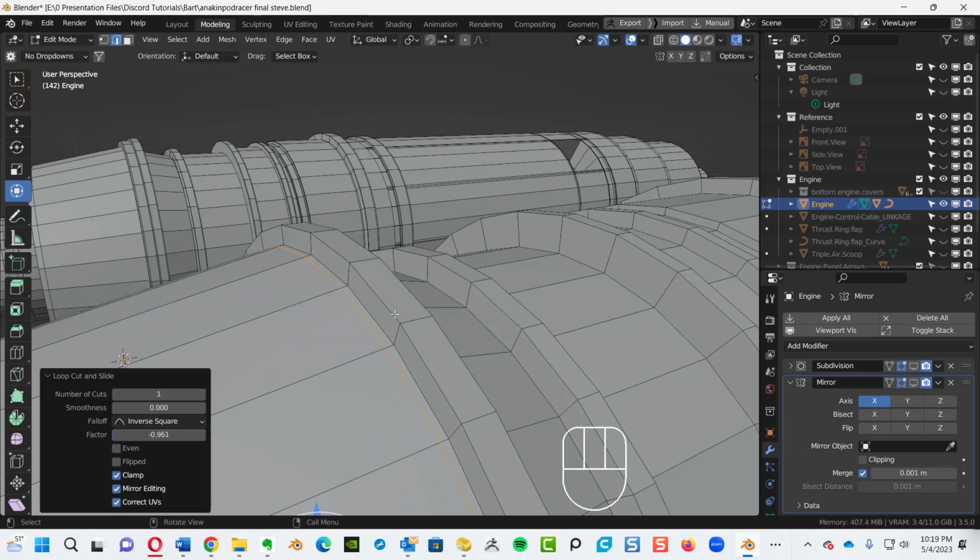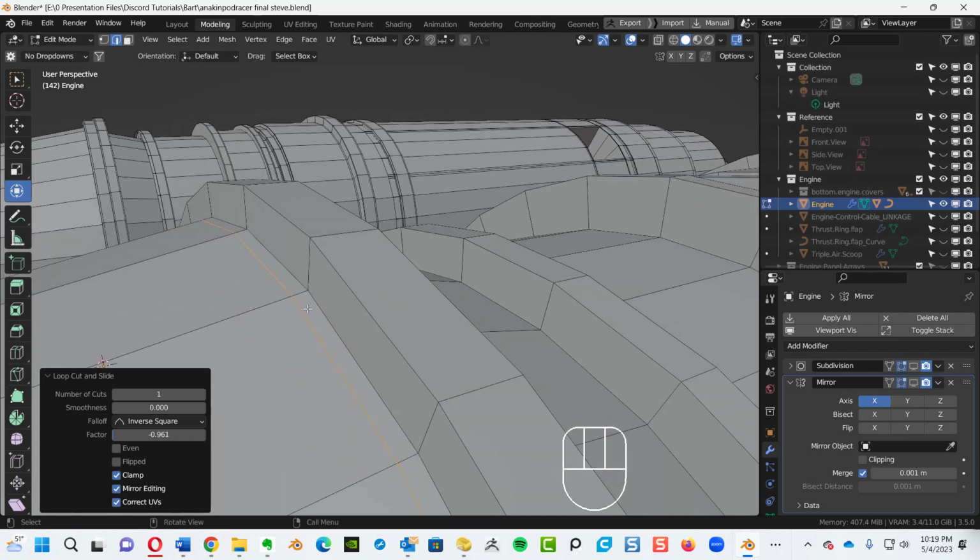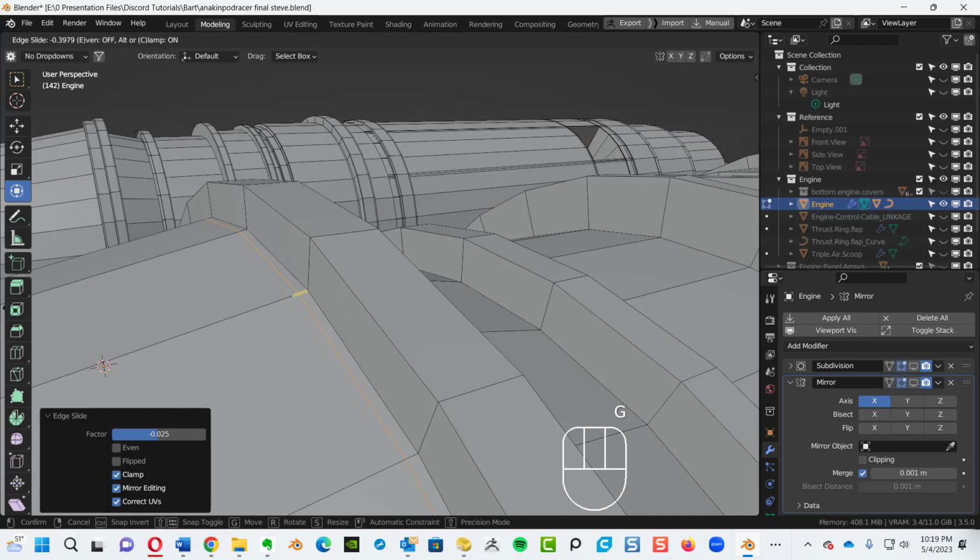Hold that edge right there. So we're looking at the edges. We're going to put edge loops on either side. That edge can be a little closer in my opinion. So double G and click and hold and push it. So double G to kind of push it a little closer. Right about there, works good.